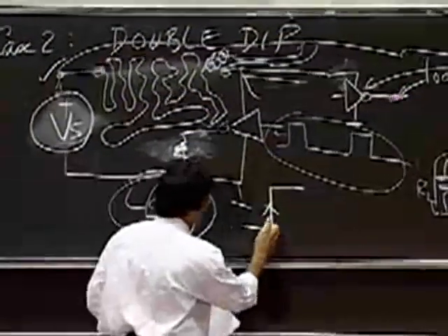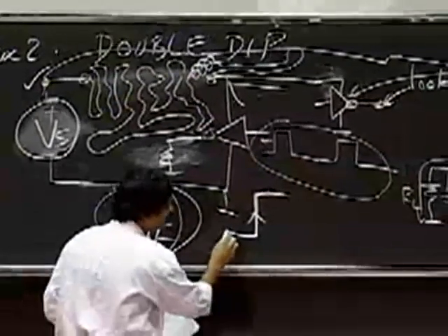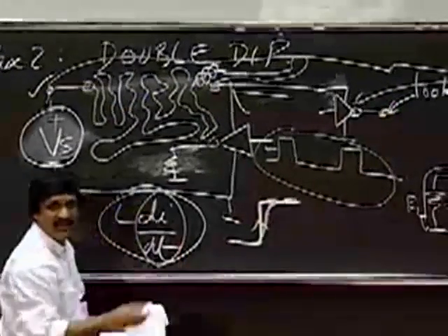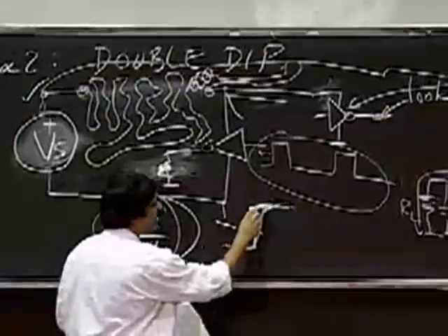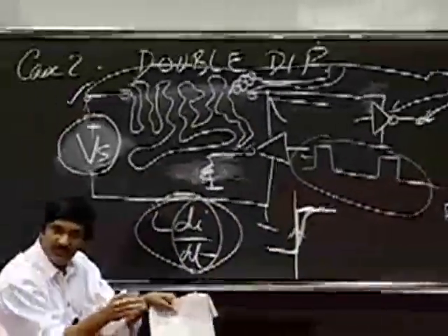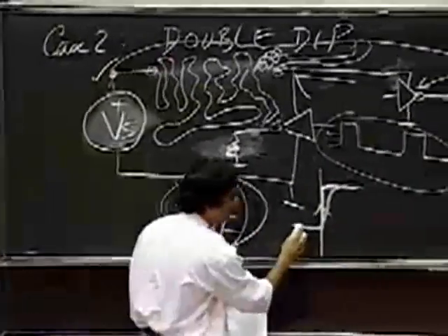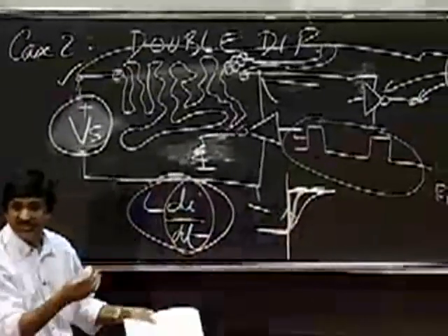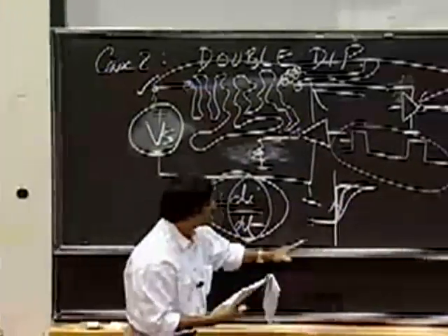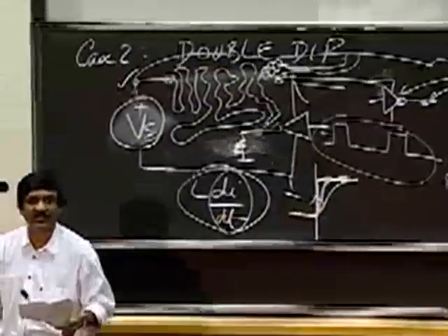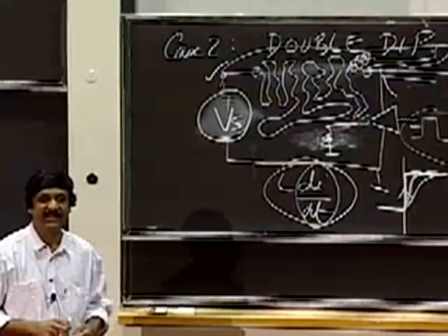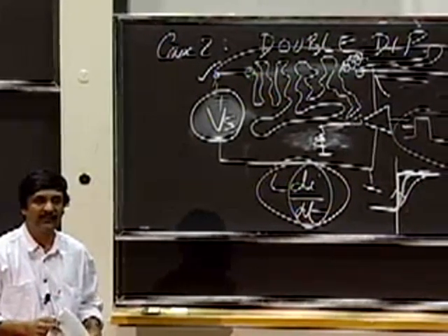The idea is that rather than have very sharp edges in your circuit, you try to have smoother edges. When you have smoother edges, your dI/dt is going to be less. It's not going to be very, very high. Rather, it's spread out; your delta I is spread out over a longer period of time. Of course, that means the circuits may have to run a little slower, but that can also solve the problem. In fact, that same smoothing of the waveforms was also the solution you saw in the capacitive coupling we saw about a month and a half ago.